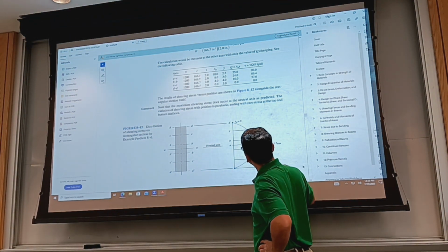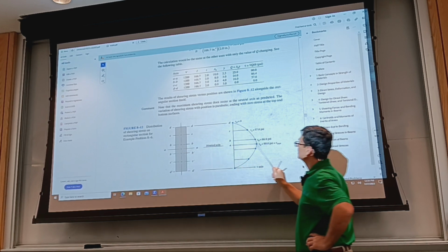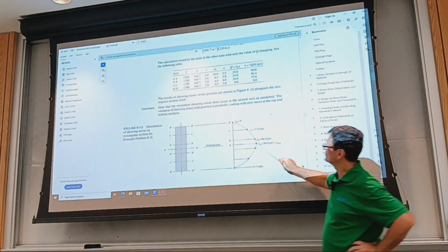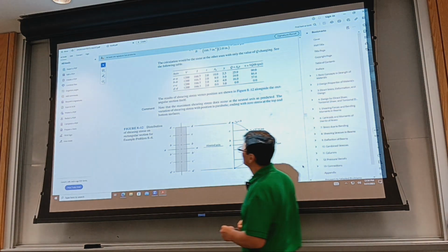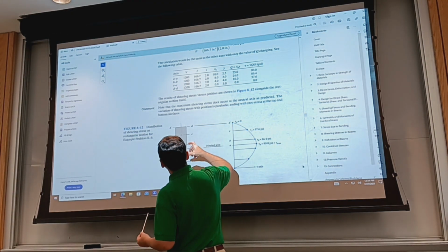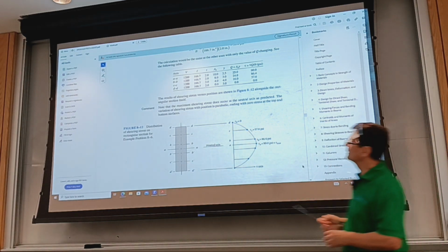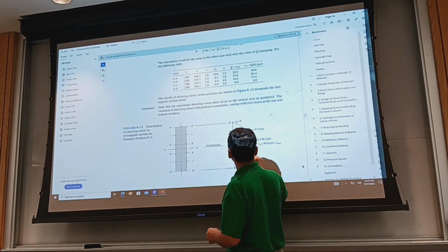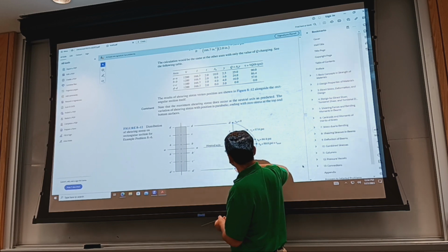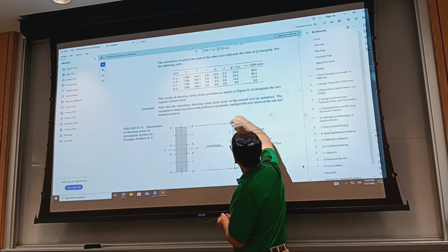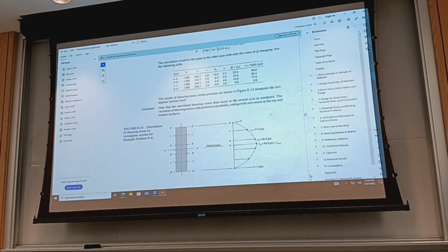They smoothen between several calculated points, and as you can see, it's maximum at the neutral axis. For this rectangular section, it's maximum at the neutral axis, while the maximum tensile and compressive stresses due to bending are maximum away from it, which again is a favorable thing overall.